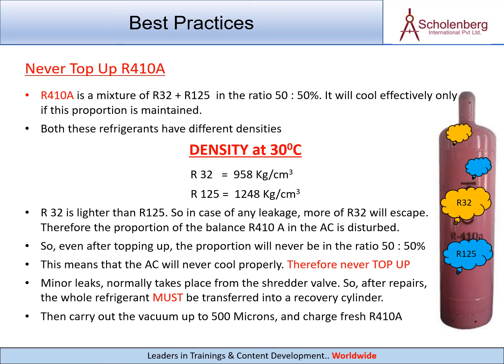Therefore never top up. Minor leaks normally take place from the schrader valve. So, after repairs, the whole refrigerant must be transferred into a recovery cylinder. Then carry out the vacuum up to 500 microns, and charge fresh R410A.